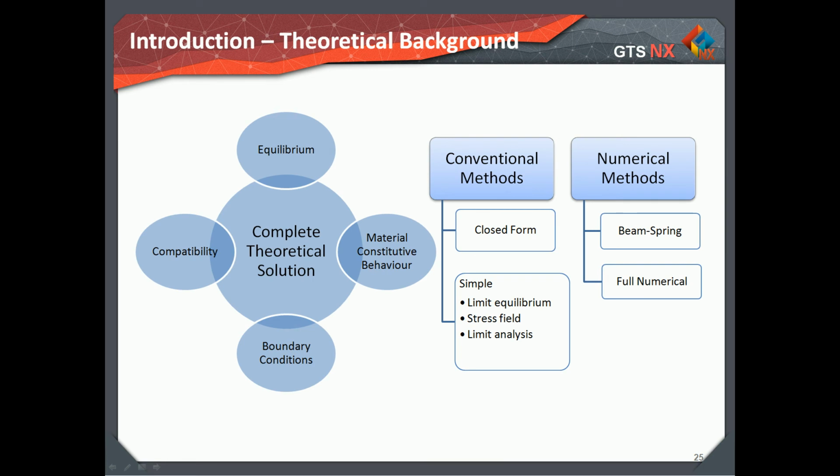To allow detailed design, a thorough analysis is used to investigate design and construction options, optimize geometry, and to check that soil and structure are not overstressed. For full analysis, the behavior of soil, structure, and their interface should obviously be considered. Mathematically, a complete theoretical solution should satisfy the requirements of these four conditions